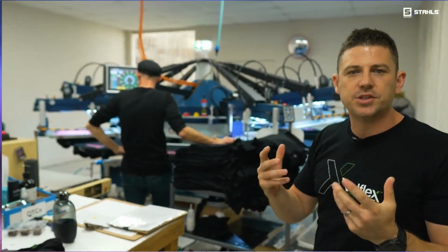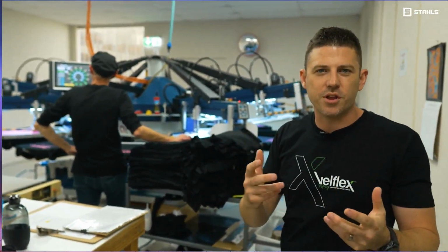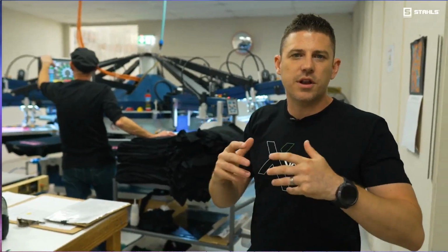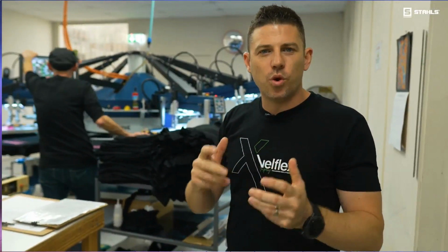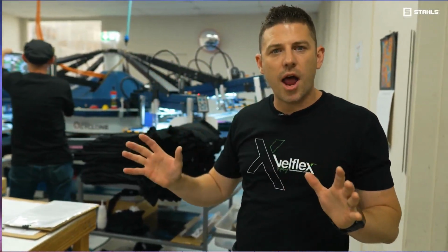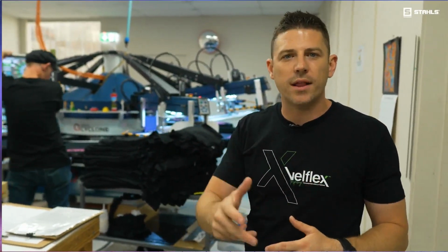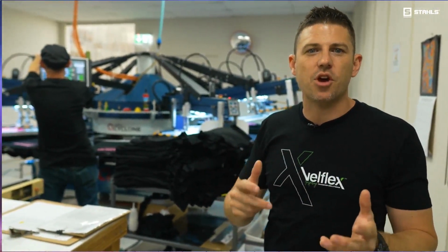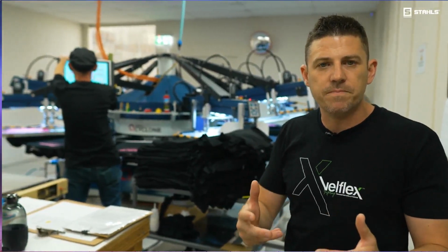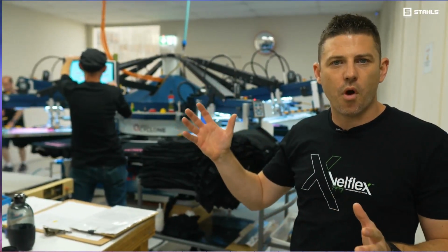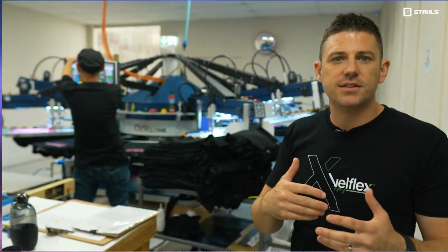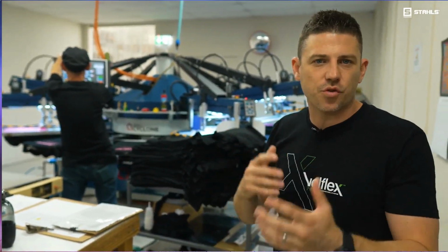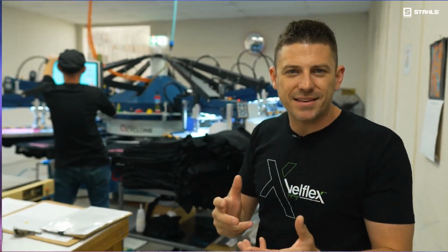Now guys, what is screen printing good for, and what type of job is it good for? It's good for those t-shirt runs, the traditional sort of garments like cotton garments and cotton tops and things like that. It's where you want fewer colors, but higher volume runs, okay? You don't want to be screen printing 1s or 2s or 5 units or even 10 units, because there's actually, as you can see, quite a lot of setup that goes into doing a screen printed job, right? So it's designed for those higher volume runs. And to keep your costs down, if you can be doing 1 color, 2 color jobs via screen print, then of course, that's where the screen printing process is best suited.